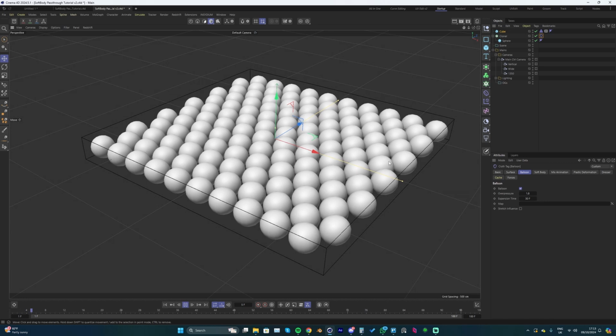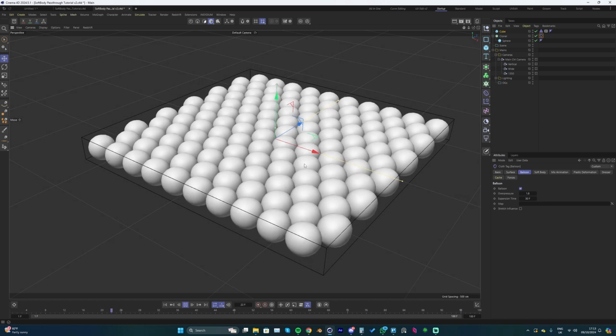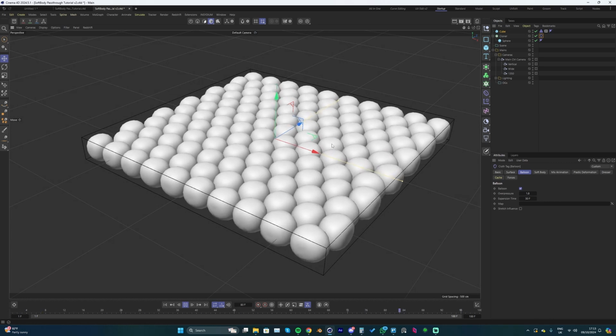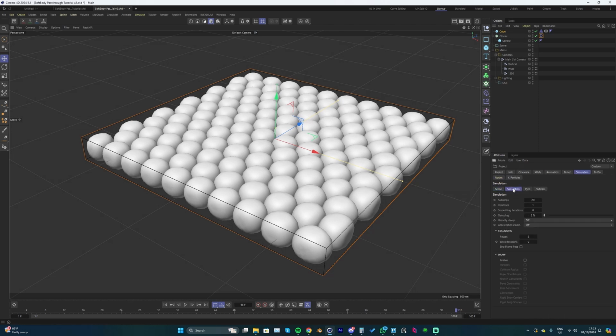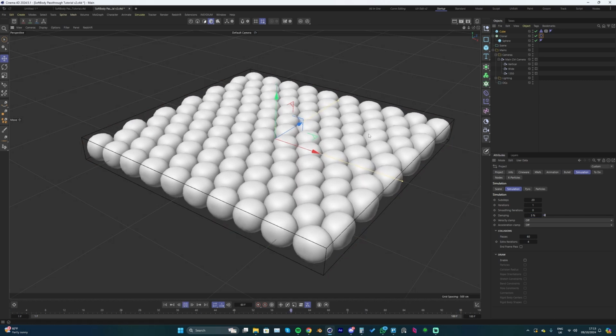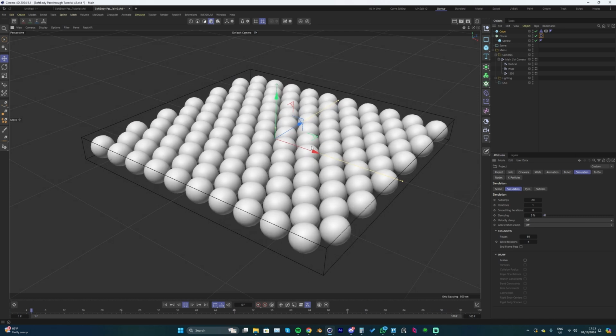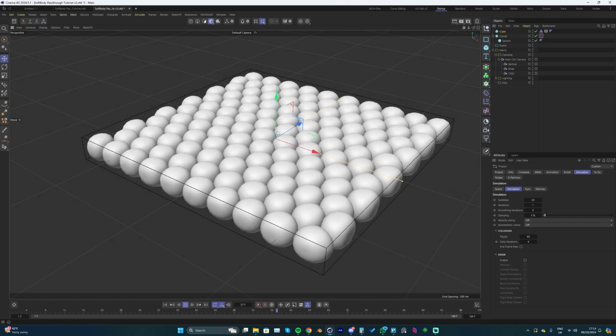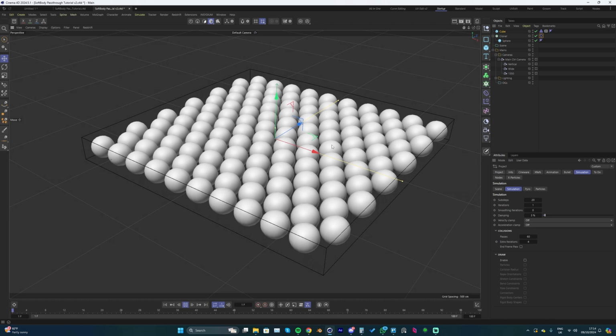And now if we click play, I think some of them are still trying to expand, which is probably why they're still vibrating, which is fine. What we can do actually is with Control D again, if we go into now simulation, we can turn this collision passes up to, let's do 60 for now, and maybe even add some extra iterations. We'll do 4, and then maybe damping to 3. Let's try that out. So it's not really making a change right now, but for when we animate our object going through all these spheres, then that's kind of where you're going to see the difference.